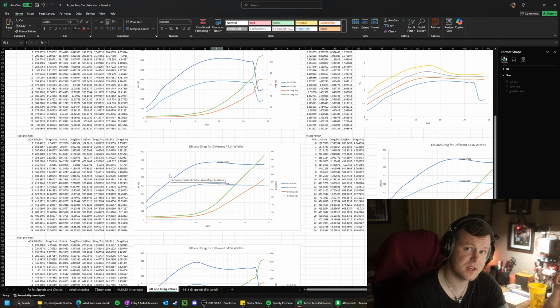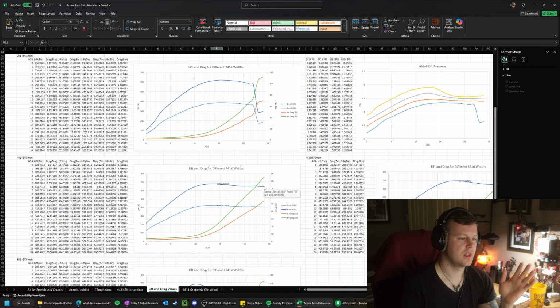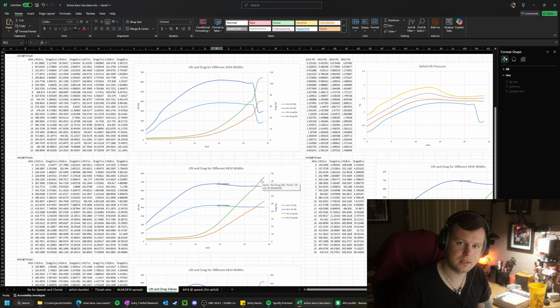So here's another thing that I also thought was interesting. The 4400 had a unique characteristic that the other ones didn't have. If you see right here, the downforce, or the lift, tops out around 670 pounds, and then it stays pretty consistent, only going down to about, what's that, 645? This looked really attractive to me because if you want to increase the drag in a braking scenario, you don't want your lift to just drop off, because then you don't get consistent downforce.